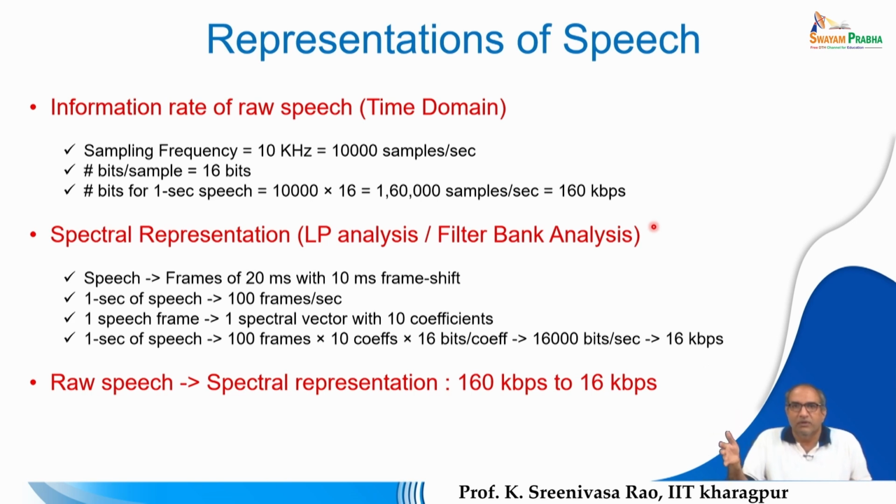And now if you represent these energy values, whatever the energies that are the outcome of each band pass filter, from filter 1 to filter 16, you have 16 values, and all these 16 values put together can be viewed as a spectral vector of dimension 16, because there are 16 spectral values. For a particular frame, we represent the spectral vector as a sequence of these 16 values put together, and it is known to be a vector, right.